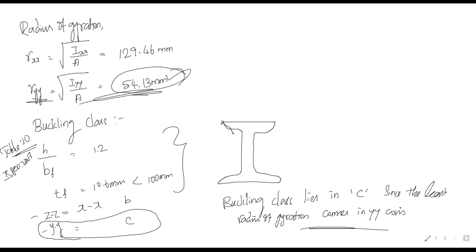Next, from the formula of the code book, PD is equal to AE into FCD. So AE we are going to have as a direct value here. There is no bolt or nut, they didn't mention anything. So 7485 mm squared we are going to take directly, but the FCD value we have to calculate.